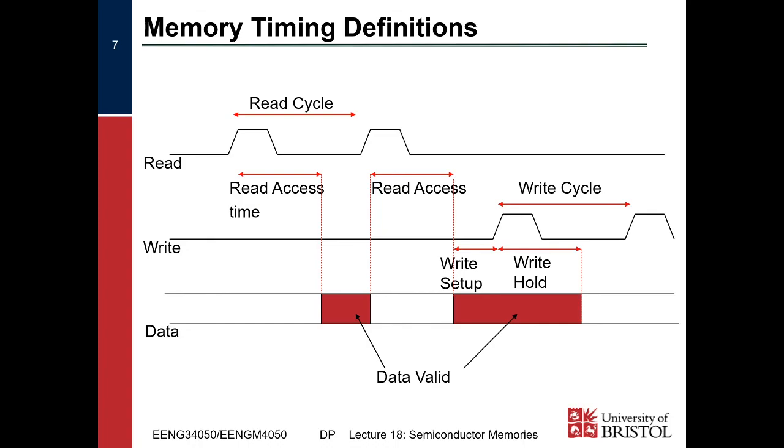Memory has timing, just as we saw with our flip-flops. If we look at the write cycles for a moment, we have a setup time, TSU, and we have a hold time, TH. Same thing as with any other type of memory. We need our data valid before the setup time, and we need it to stay valid until after the hold time. Otherwise, our memory might do something weird.